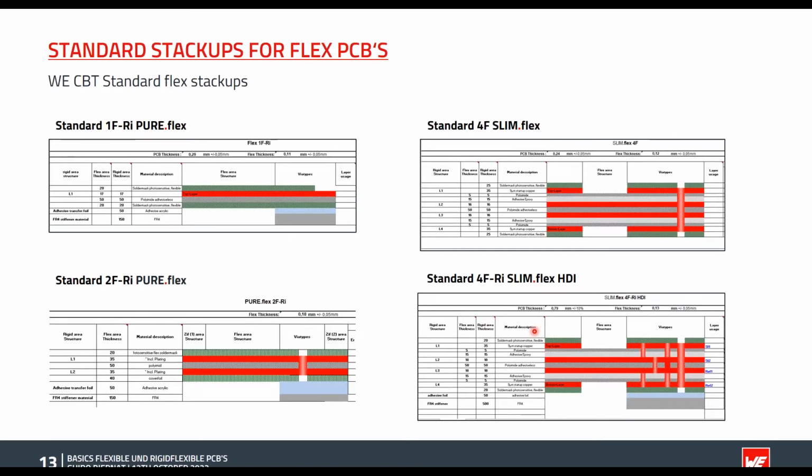For the next stack-up, you can see that the 4F slim flex HDI is also possible. We have the same materials, but we have microvias from the top side and from the bottom side. We have buried vias, inner layer core, and through holes, and also we have stacked vias from top to the inner layer.